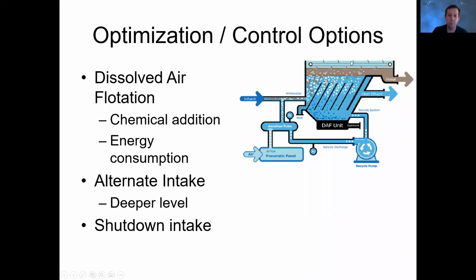So we see where the water comes in on the influent side here, that there's a couple of contaminants in there. They're going to go through these corrugated angled plates, and then air bubbles are going to come up from the bottom. Those air bubbles will grab any particles, either be solids or they'll be algae or oil, and they'll float them to the top because they're directly in contact with those particles. The smaller the air droplet or air bubble, the easier it is for it to grab something and float it.